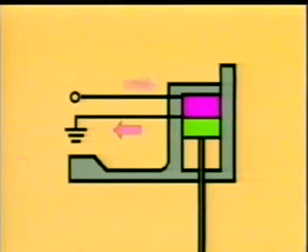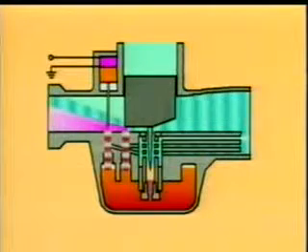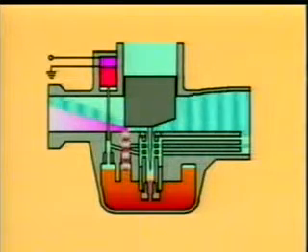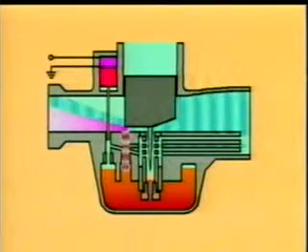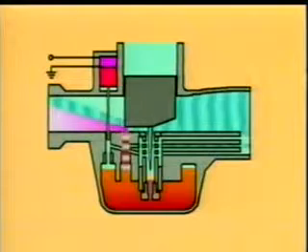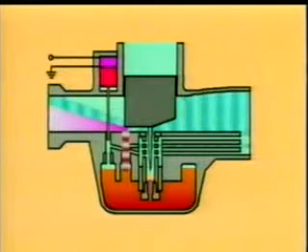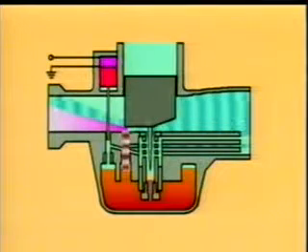The engine is then started up and the current produced by the generator begins to flow to the heater, which gradually warms the wax so it begins to stretch. When this happens, the starter valve begins to shut off the passage little by little, decreasing the amount of fuel dispensed until finally, only the fuel-air mixture from the pilot system is being supplied to the engine.